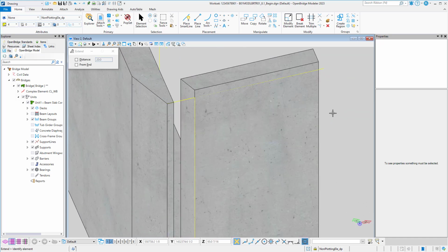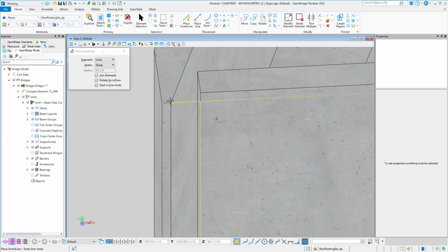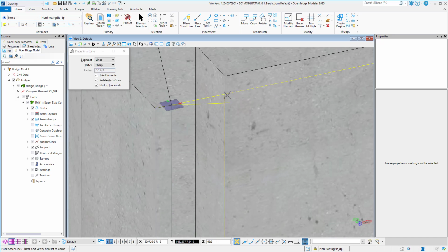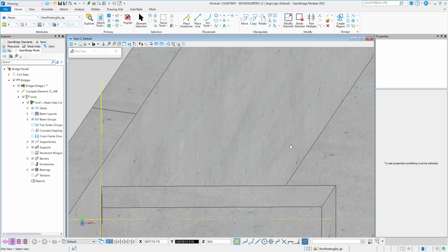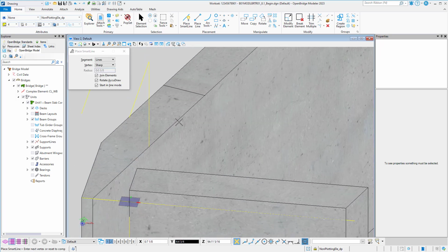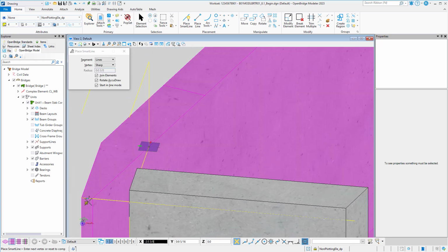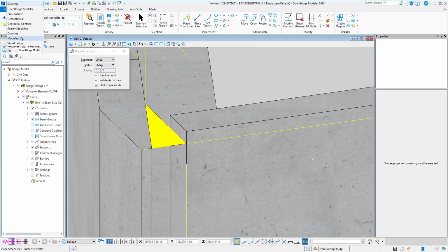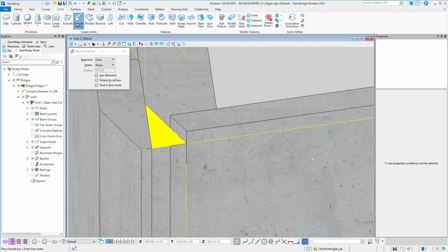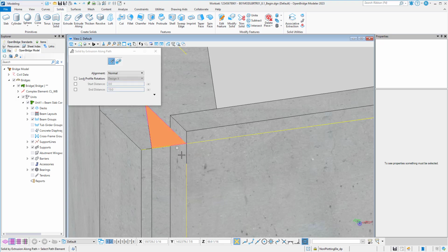The last step is to now create the 2D surface that we want to extrude along the extended line that we have modified. To do this, I will use the Place Smart Line tool again and the points shown to create a surface. Once that surface has been created, you can navigate to the modeling workflow, where under Solids you will find Extrude Along. You can then use that Extrude Along tool to create a 3D element based on the surface that you have created.